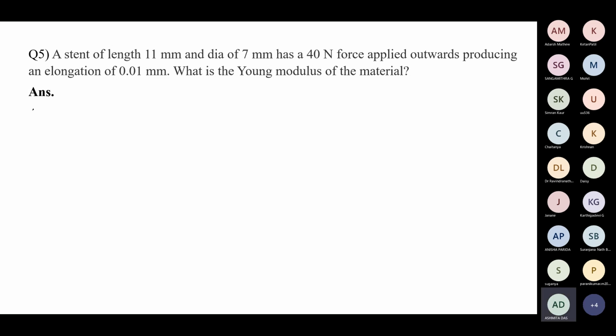Okay, moving to the next question. A stress of 2.5 megapascal is required to stretch a 1 centimeter tube to 1.1 centimeter. After 2 hours in the same stretched position, the tube exerts a stress of 1.5 megapascal. What is the stress relaxation time in hours? Others and Ketan, please put down your hands.